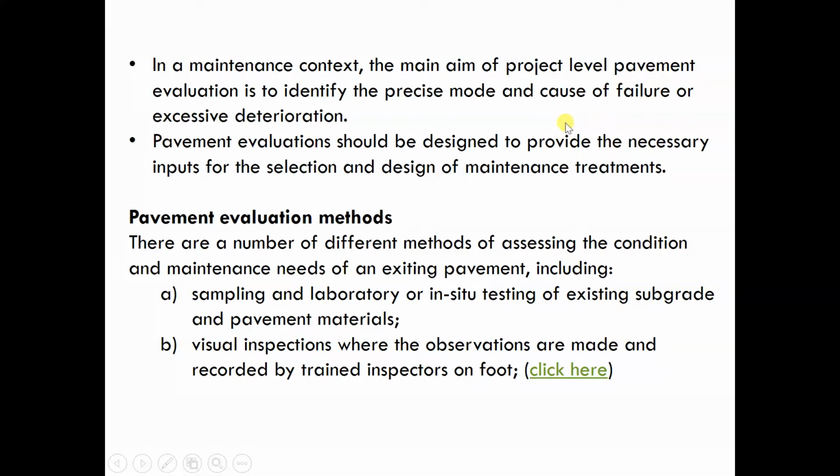If you can't do it by visual observation, you might have to do testing, like in-situ testing, or do some coring and then bring it back to the lab to be studied. Pavement evaluation should be designed to provide the necessary inputs for the selection and design of maintenance treatment.